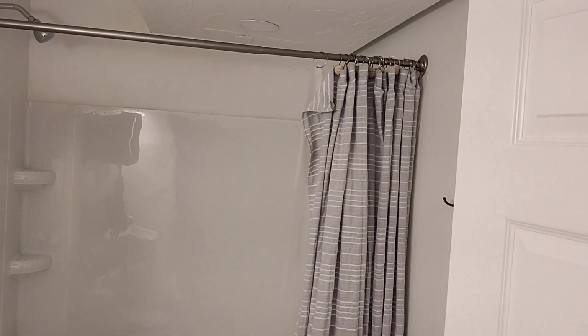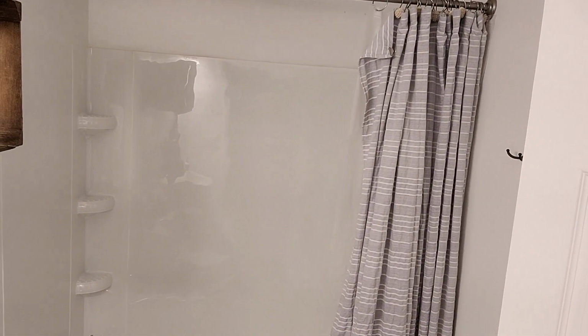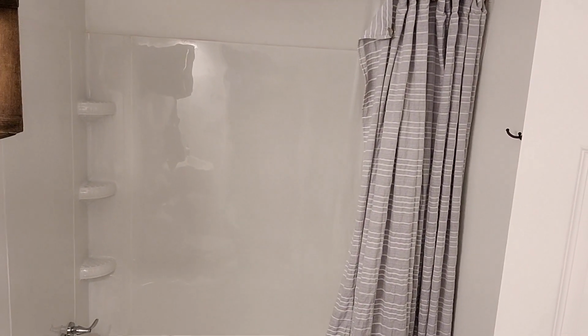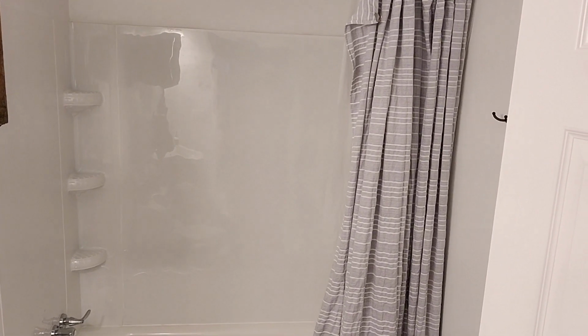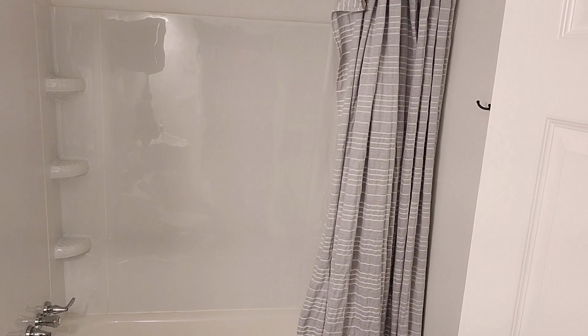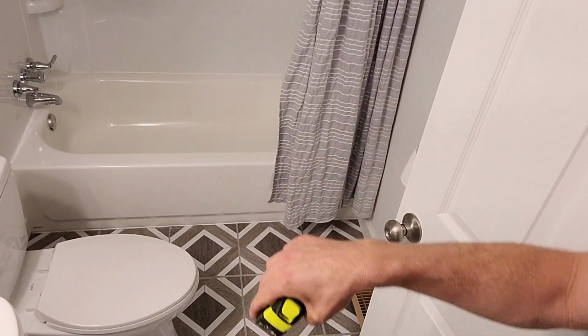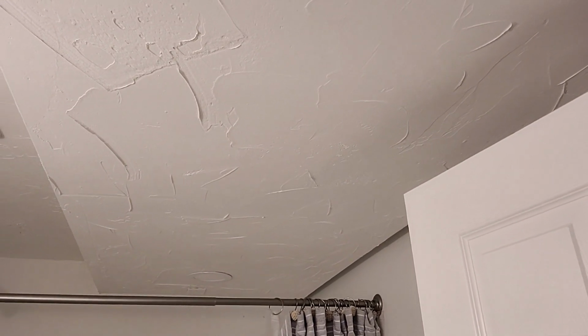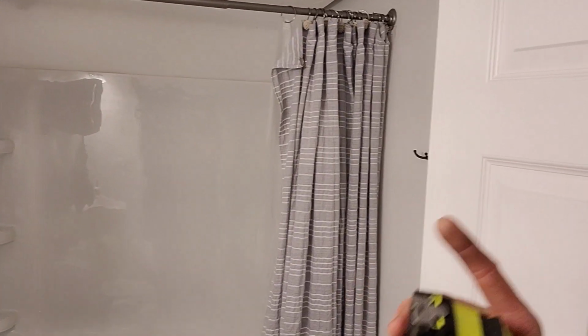Moving on to the bathroom. Again, this is a standard small bathroom. Nothing crazy going on here. We want to take a look at where we can get air into this room. We're not going to focus on a return at all, because you do not put returns in a bathroom. The only place that the air is coming out of this room is through that exhaust, okay?